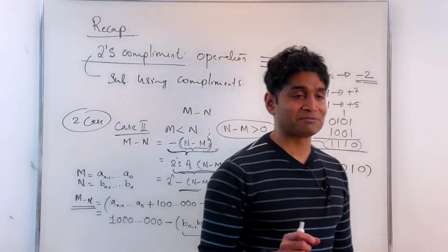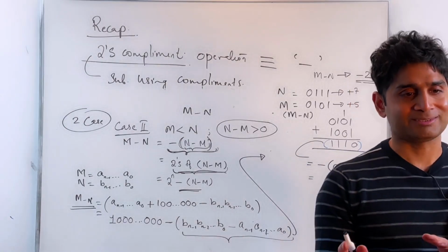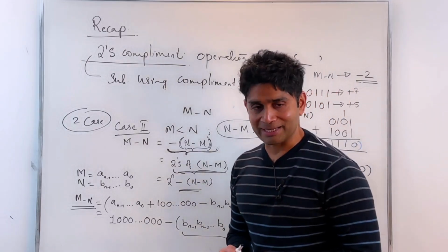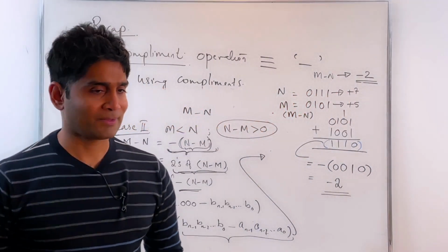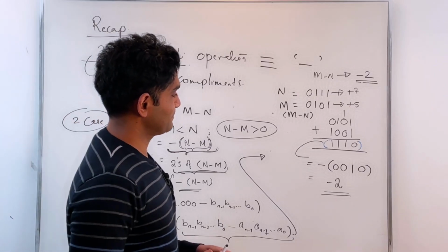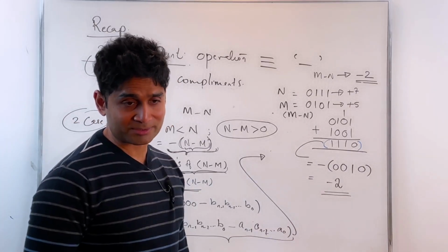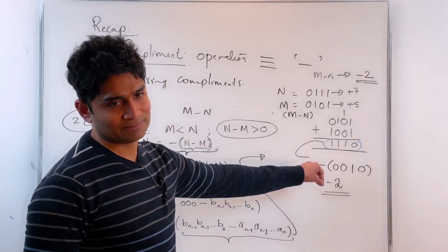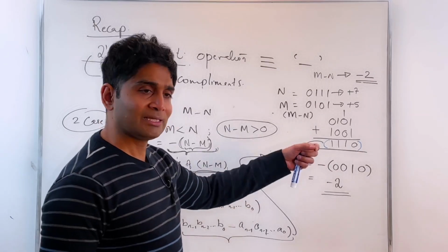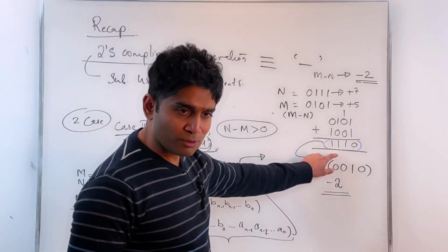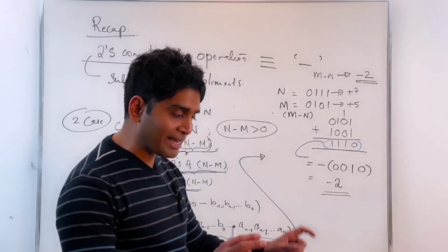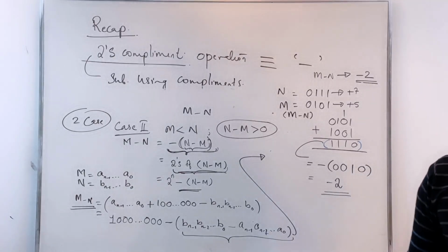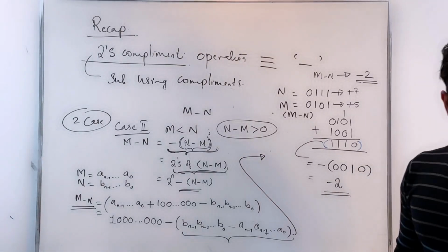So again, very important: you should not get confused between the two approaches. Keep track of that. So that's negative 2, that works. Does it make sense? The answer is automatically in the right format. If it's a negative answer, it is already in the correct format. As long as I do not have an overflow, which we considered in the last class, this operation works under all circumstances.